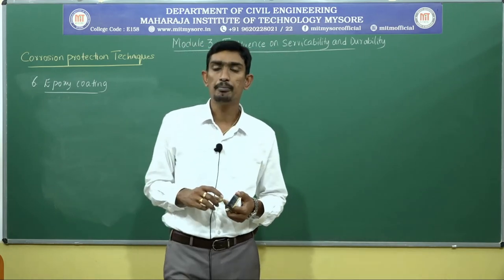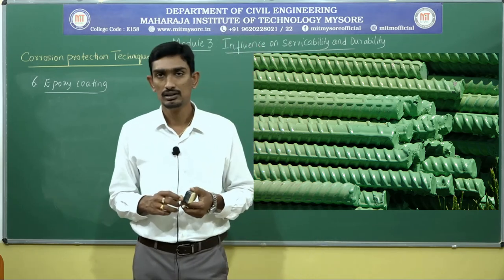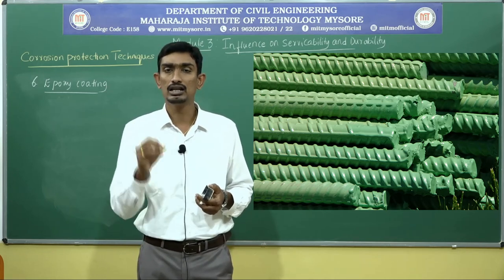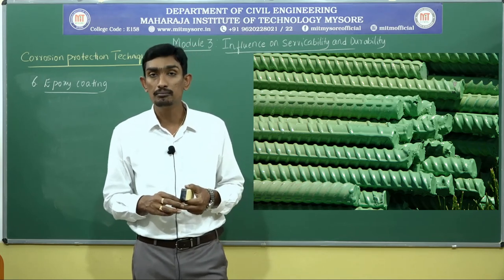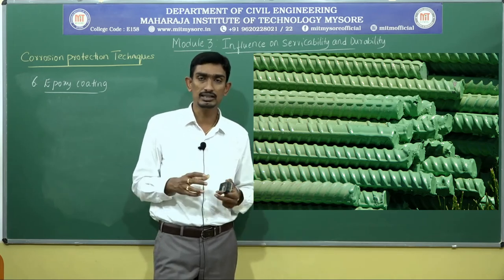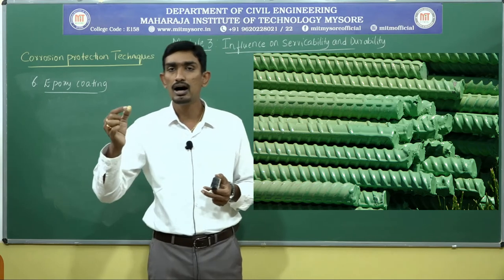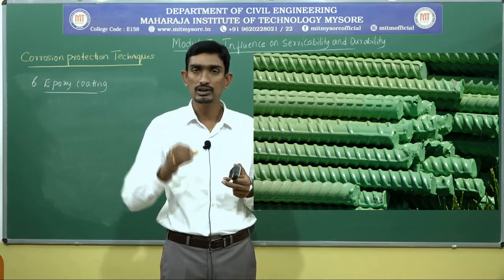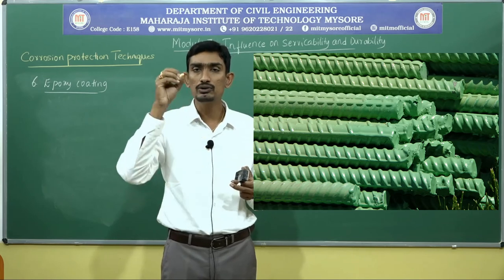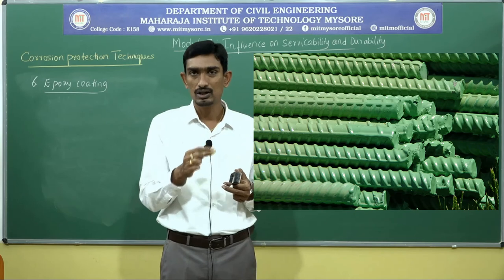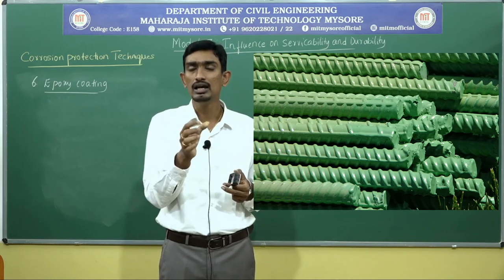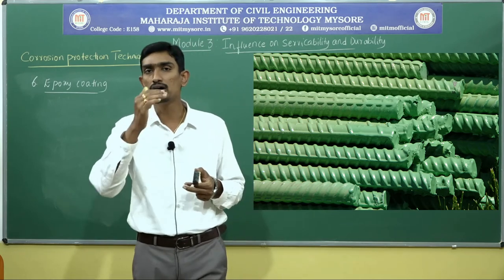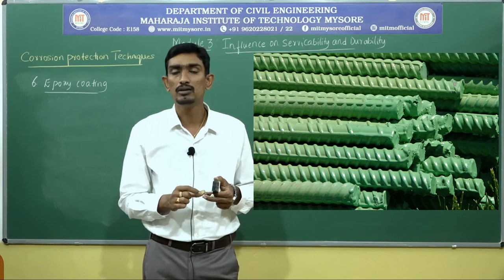First of all, epoxy is a polymeric material. It is a resin, a polymeric resin. This epoxy will be laid on the surface of a reinforcing bar as a powder material. The process is such that a rebar is sent inside the epoxy bath. In that bath, they spray the epoxy to the required thickness, so that the epoxy in powder form is laid on the rebar with sufficient coating thickness.